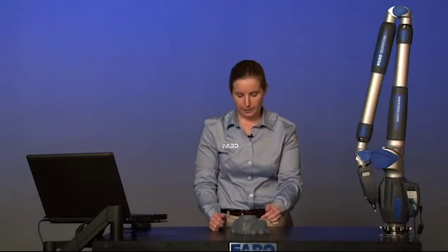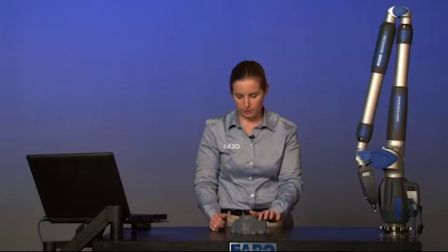The key to making these parts match up and line up within the software is making sure you have overlapping data. We've gathered overlapping data in the areas of the part near this section where you see the letters that say variable, and near the lower section where the serial number of the part is. Now in the software, I'm going to join these together.